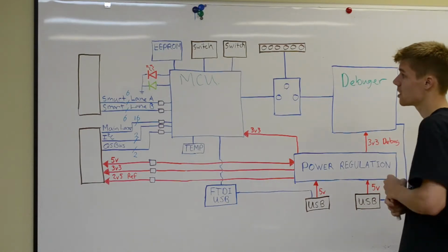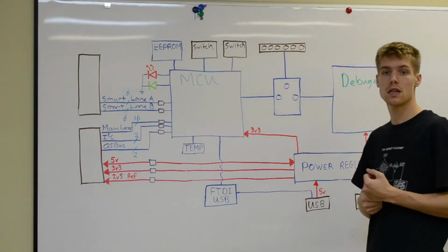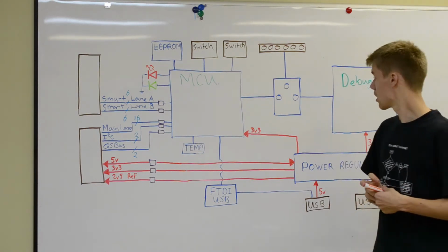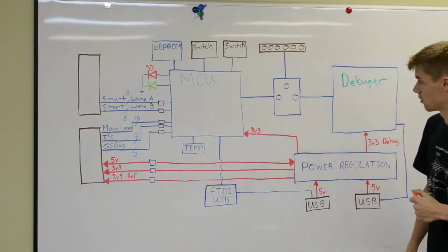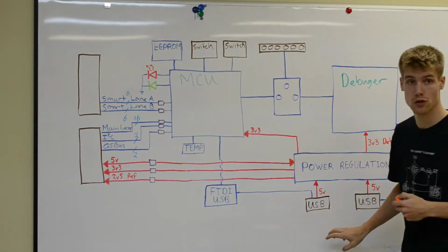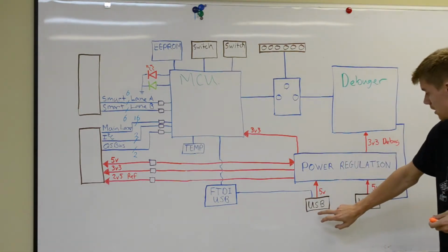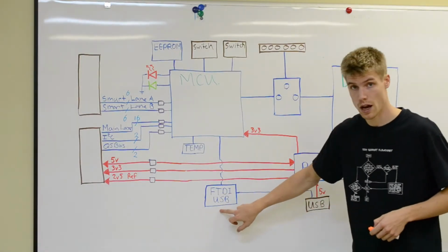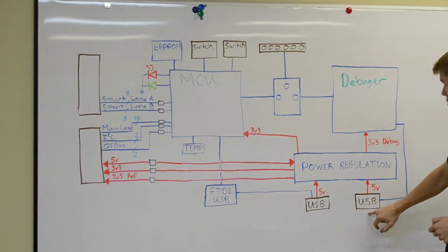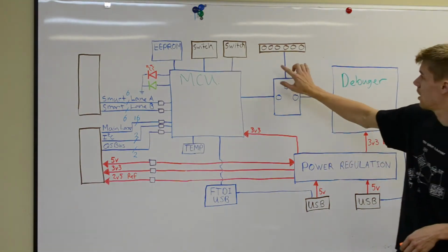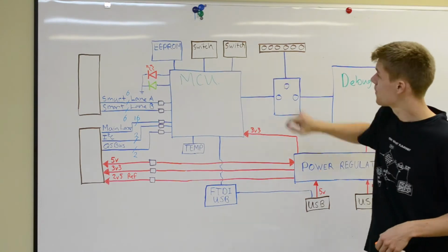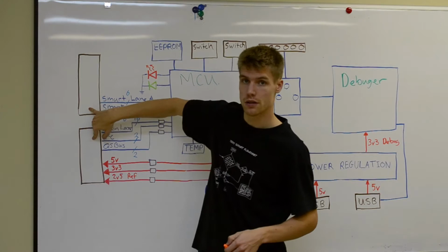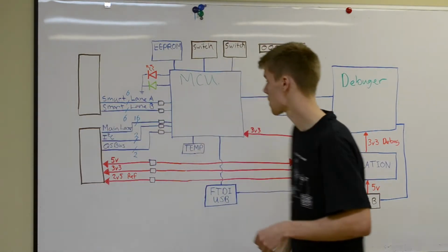Hi guys, this will be a quick overview of the top-level block diagram of the QuickStack Hello. To start off with, in brown, we have all the external connections. That includes one USB connection for the FTDI interface, one USB connection to connect to the debugger, an in-circuit serial programmer, two switches, and the QuickStack interconnect headers.